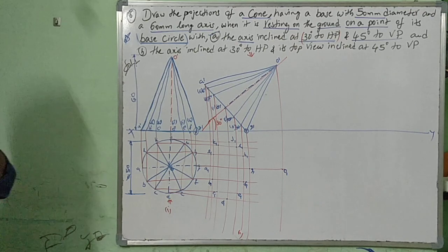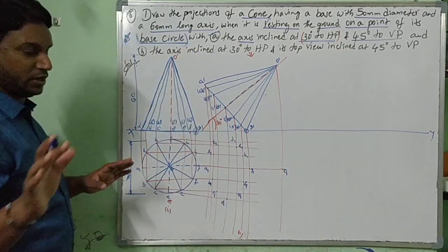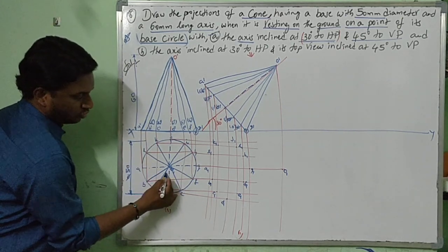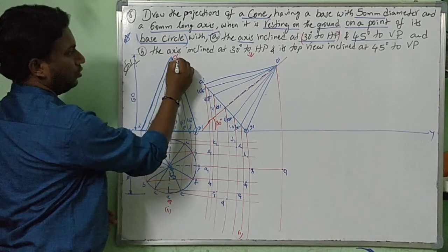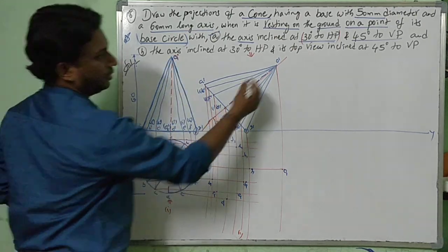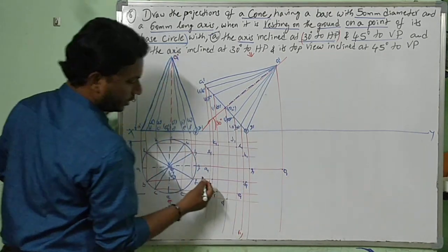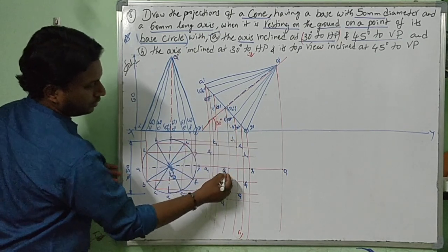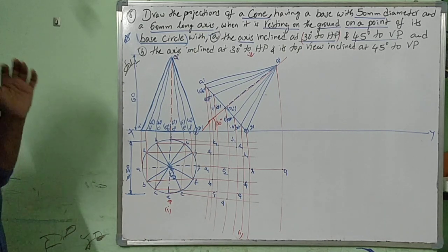Now O to O center line here, O1. New point. Base I have not given. Right? If you still want to avoid this confusion, if you want to go for two bases, axis, here I can write it as O1 in brackets O2, which is inside. Now here O1 dash, O2 dash in brackets, which is bottom. Here O1 dash, O2 dash bottom. Here I can write O1, O2, let's plot. Now here comes O2. It will avoid confusion in drawing the axis.